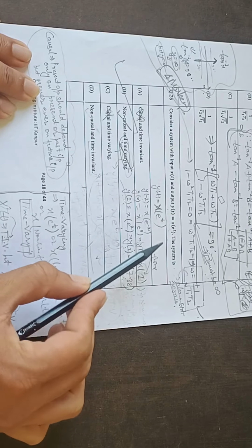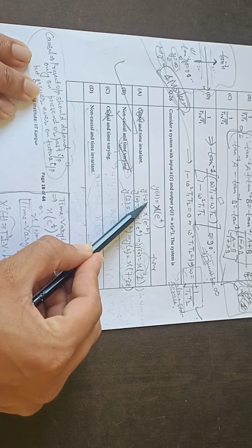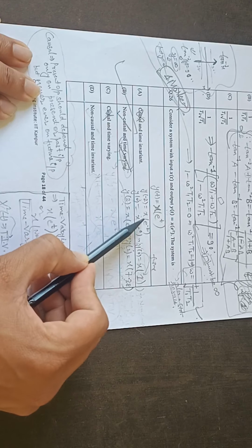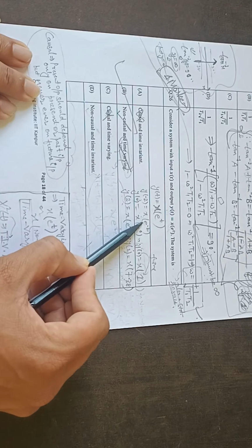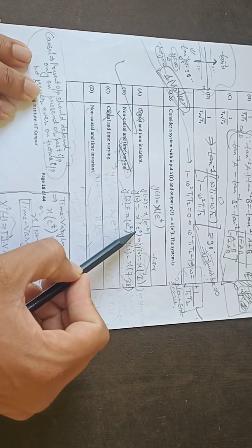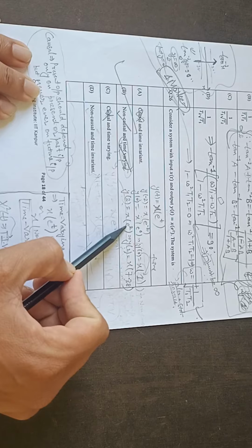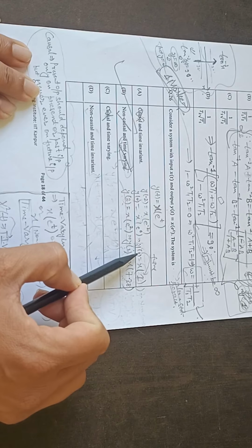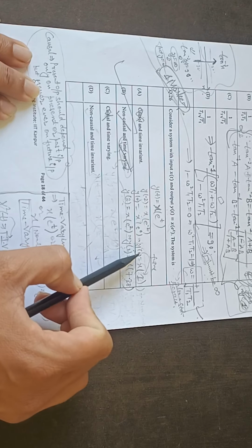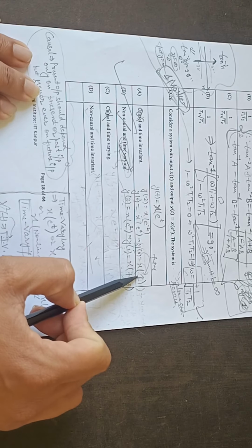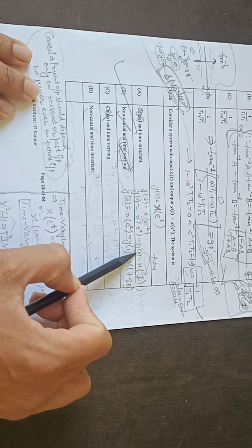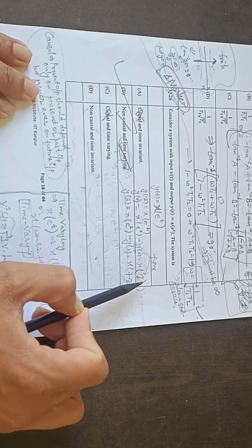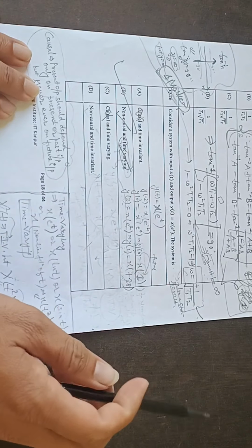To check causality it is very easy, just put three values: y at t equal to -2, y at t equal to 0, and at t equal to 2. So at t equal to -2 it is x(e^-2), then x(e^0) and x(e^2). So y(0) is equal to x(1). Basically the output at t equal to 0 is demanding the future input value at t equal to 1. So to find y(0) we need x(1). Present output is depending on future input values, so it is a non-causal system.